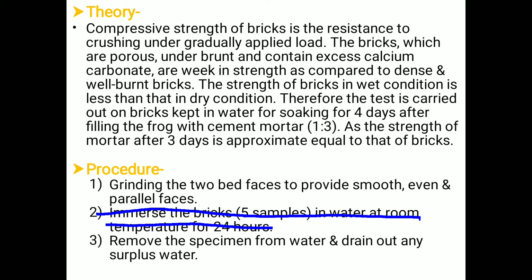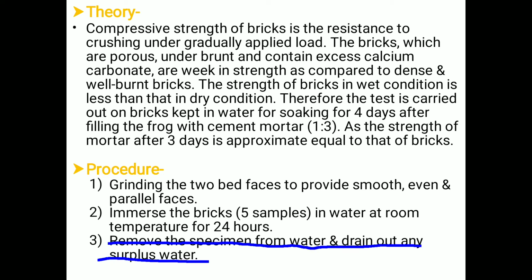After 24 hours, remove the specimens from water and drain out any surplus water. If any surplus water is there, then we have to wipe it.